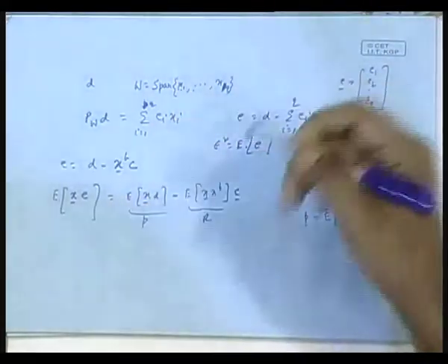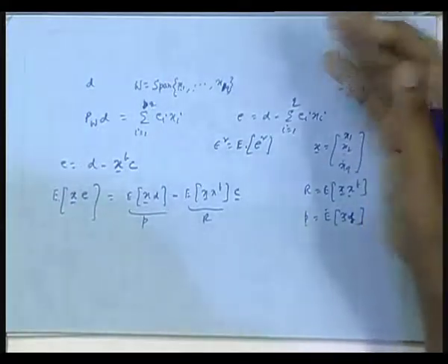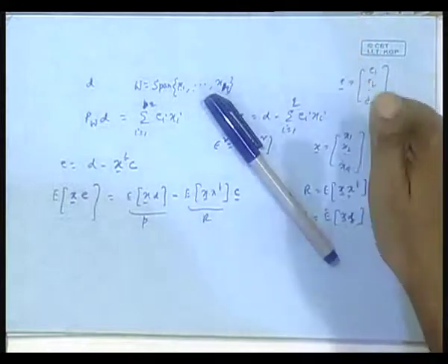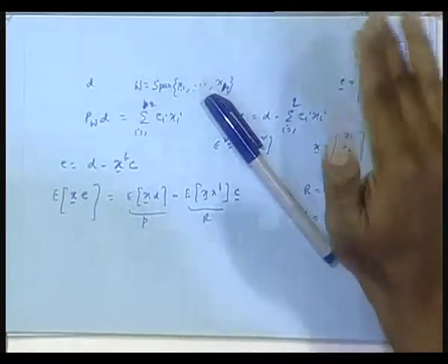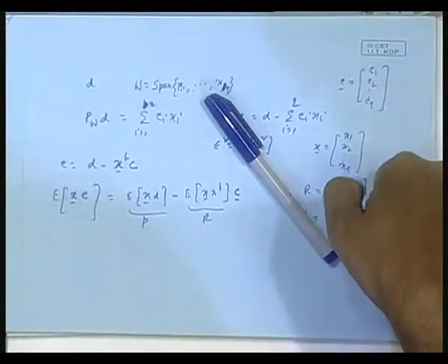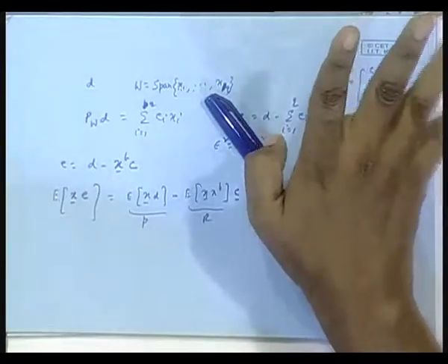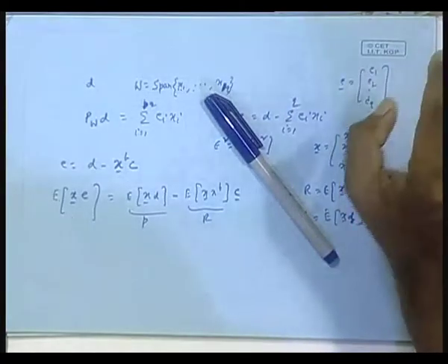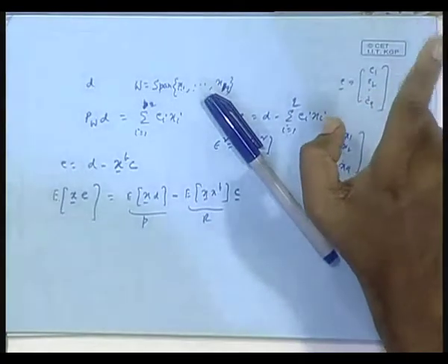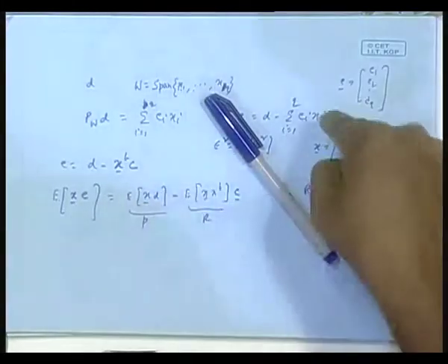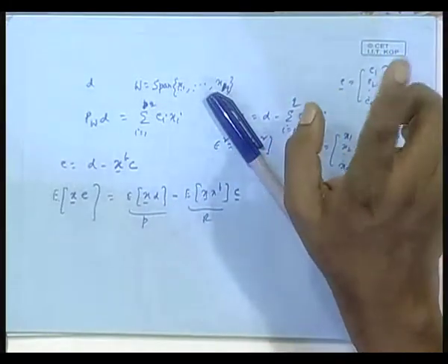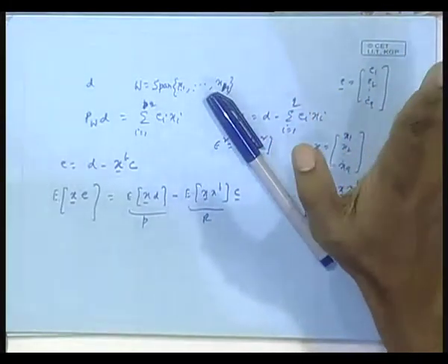After sufficient runs, there is a steady state, and usually after 200, 300 iterations you find steady state, and at that time each of the filter coefficients will fluctuate, but the fluctuation will be around the optimal value. But at least convergence is taking place, but not absolute convergence, not exact convergence, convergence only in mean. That is the price we pay, because I injected those approximations in the beginning. R and P were replaced by very wild estimates. So, number one was that we are not getting absolute convergence, we are only getting convergence in the mean.